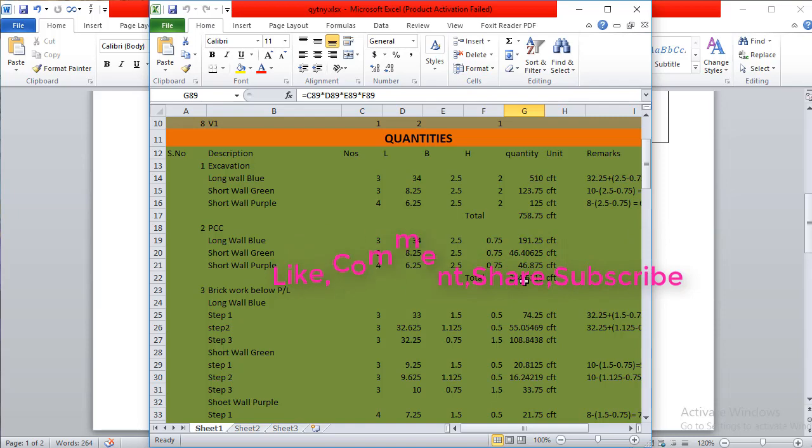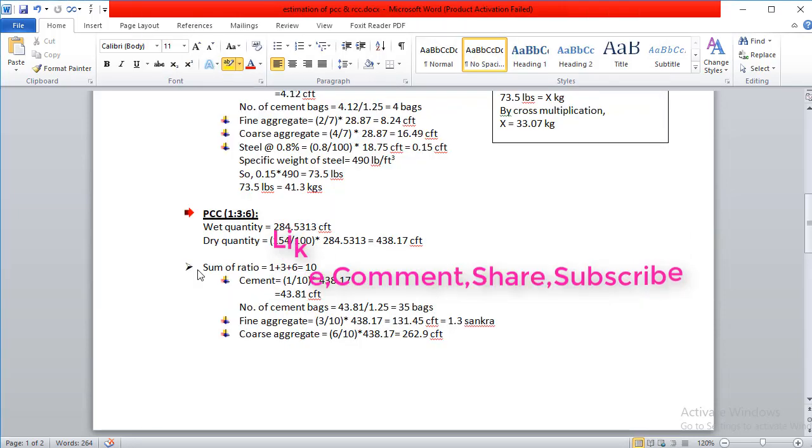Okay, so I just simply copy it from here and paste it right here, and the dry quantity will be the same, 154% of the weight quantity, so 154 divided by 100 multiplied by 284.5313, and you will get the dry quantity of that PCC. Now take the sum of the ratio, which is equal to 1 plus 3 plus 6. Here the ratio that I have selected for PCC is 1:3:6. 1 is for cement, 3 is for fine aggregate, and 6 is for coarse aggregate. So the sum of ratio is equal to 10.